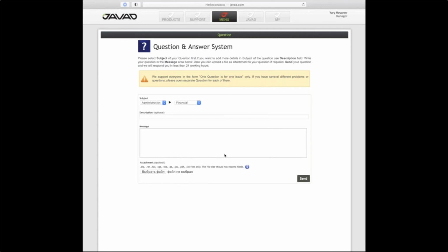Okay, let me answer. GMT includes a surface takeout feature. For this, TIN structures can be used as a target. The data can be imported either from LandXML, TIN mesh, triangle mesh, or from DXF 3D format from AutoCAD, including triangles in the TIN structure.